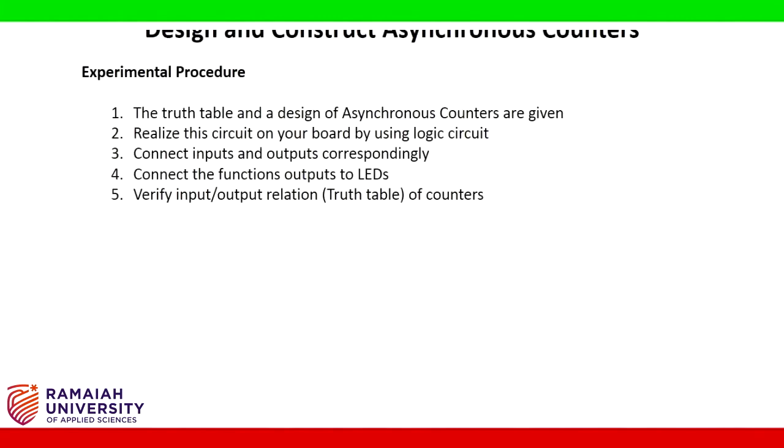Procedure for verification of asynchronous counters. The truth table and a design of asynchronous counters are given. Realize this circuit on your board by using logic circuit. Connect inputs and outputs correspondingly. Connect the functions outputs to LEDs. Verify input-output relation, that is truth table of counters.